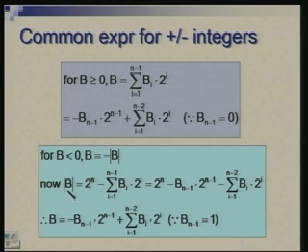Since it is a negative number in 2's complement representation, the magnitude is 2 raised to power n minus the weighted sum of the bits. This sum is the interpretation of that number had it been an unsigned integer.